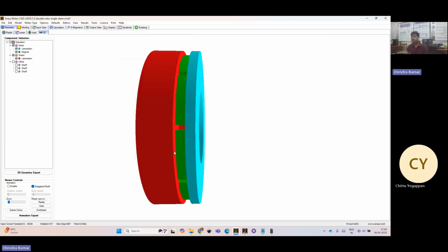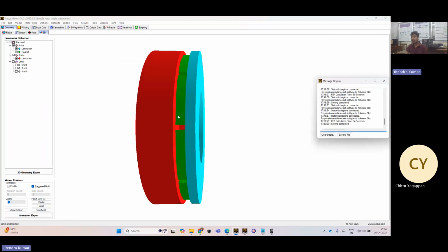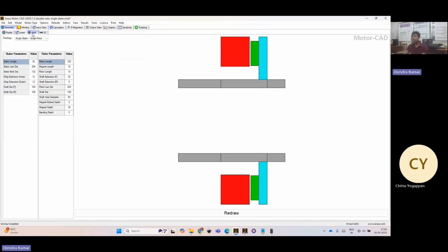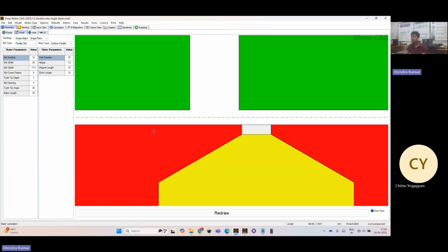as I mentioned in one of my lectures, is unequal forces, right? This magnet will try to attract this iron core, isn't it? Or this rotor core will be vibrating, or it will not be balanced at its own position. So we need to maintain this air gap in between uniform, this air gap must be uniform.